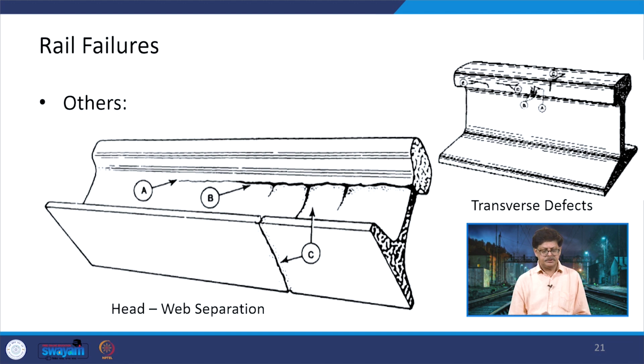Here again you can see that this crack is continuously going. Along with that, there are cracks which are going in this vertical direction, and this crack has then finally come to the flange, and the whole flange is getting cracked. So, there is a possibility, as in one of the diagrams we have seen, that though the rail head is good, this portion has chipped off.